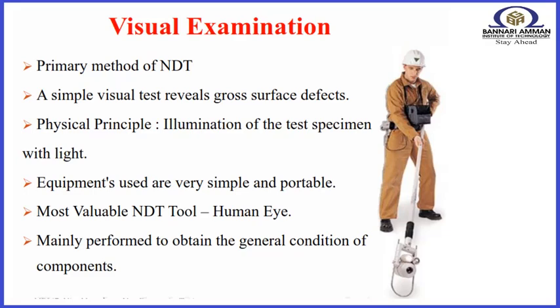While direct visual inspection is the most common non-destructive examination technique, many other NDE methods require visual intervention to interpret images obtained while carrying out the examination. For instance, penetrant inspection using visible red or fluorescent dye relies on the inspector's ability to visually identify surface indications.